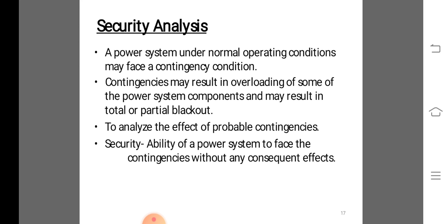Then the state estimator uses real-time status and analog measurements to determine the best estimate of the state of the power system. It uses a redundant set of measurements, calculates voltages, phase angles and power flows for all components in the system, and reports overload conditions also.